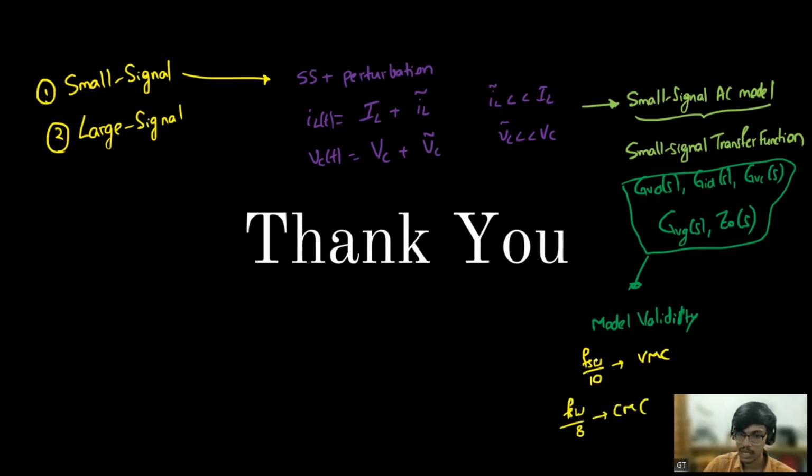This limits our controller to operate at a bandwidth of 1/10 of the switching frequency in voltage mode control and 1/8 in current mode control. Say if I want to achieve a faster response, I cannot use this model, because the model itself is not valid.